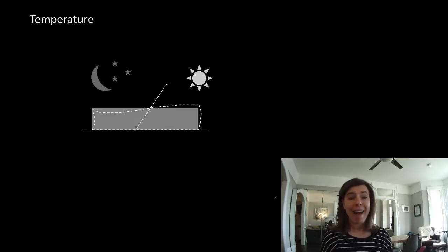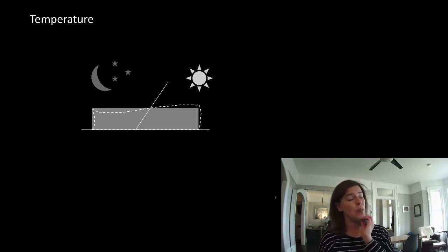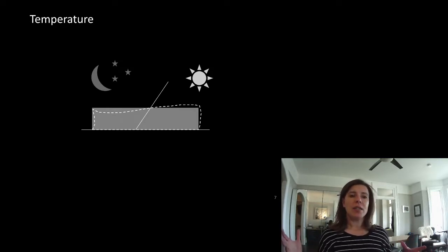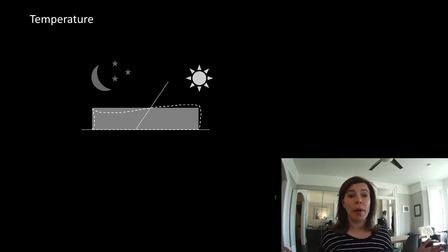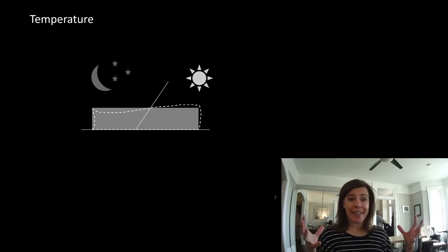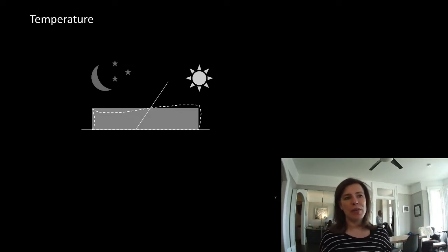The window guys came back that day and were like, no way, it's all still so off, we cannot install these windows. So what was happening was, it was fall, and you guys know that, especially here in southern Ontario, you can get long shadows and cold nights. So the site was in shadow, and it had been a cold night, so it was like -5 in the morning, and then the sun came out, the shadow moved off the building, and it turned into like a 25-degree day. And so the steel all swelled or expanded somewhat, and so the windows didn't fit.